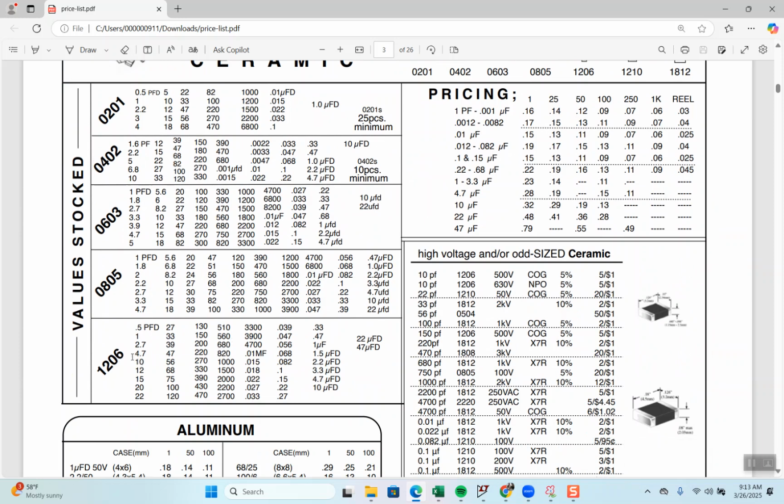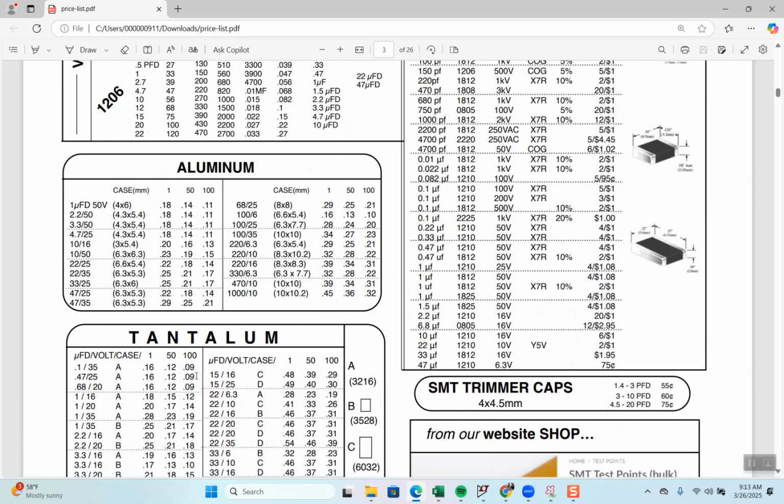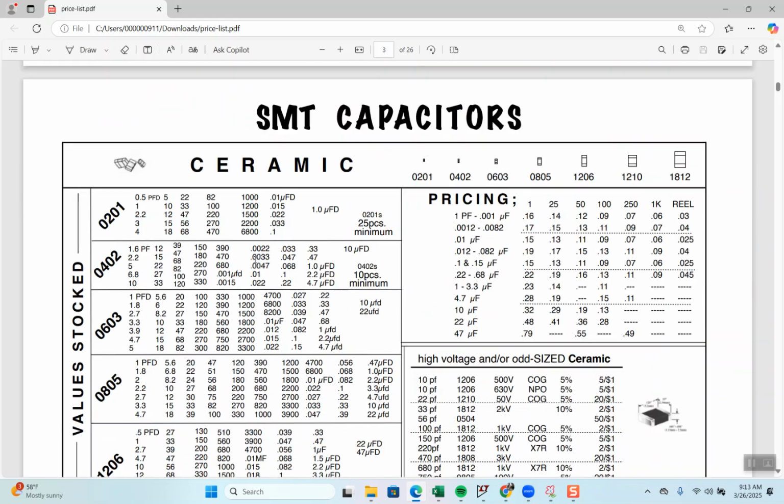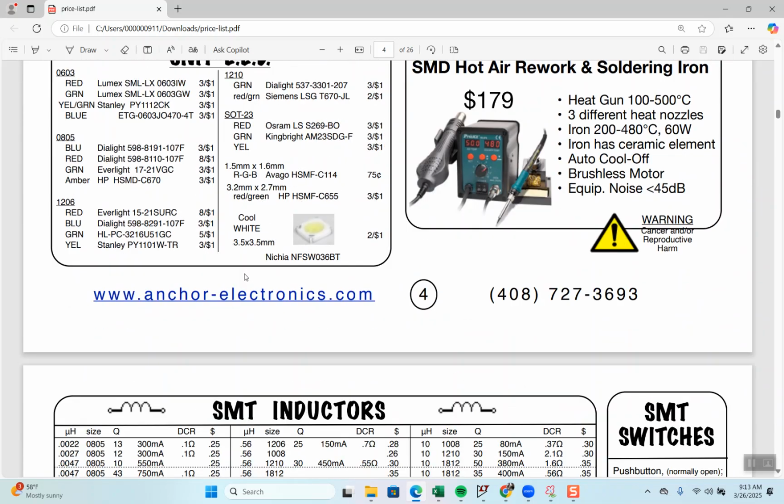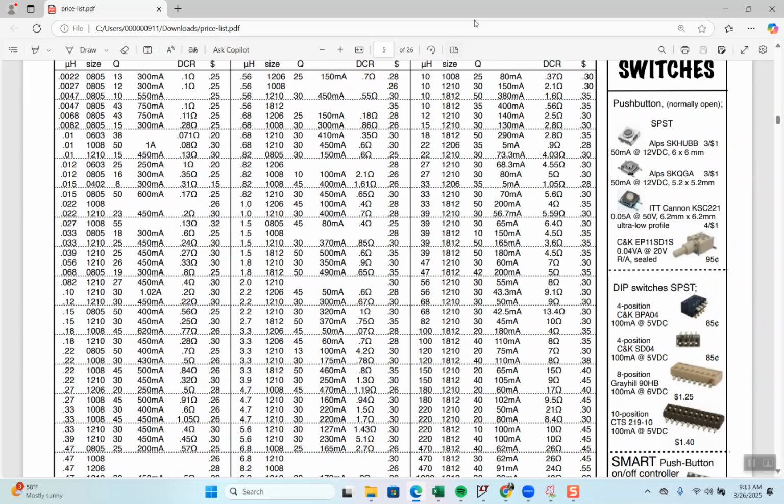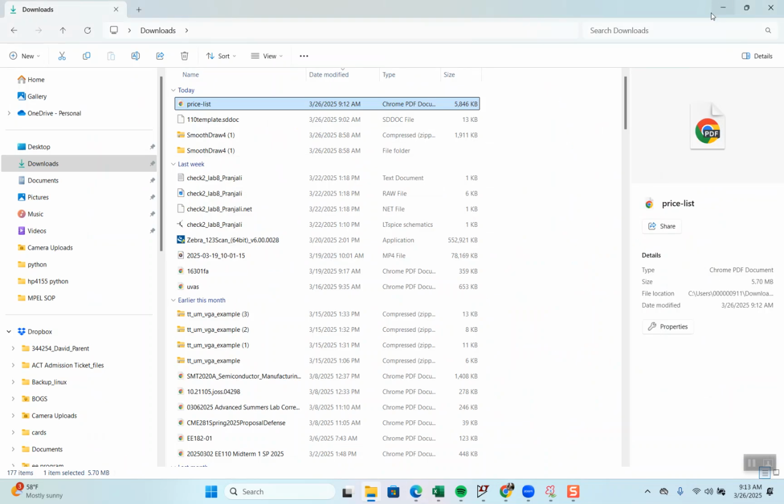And the 1206 has more choices, but that's only because they can be larger, right? So the 0.51, 2.7, 4.7, 10, 12, 15, 20, 22, right? That's kind of the pattern that you can get. And the same with inductors, which are even more limited, okay? And in one of the notes, I just have a capture of this for the relevant thing, all right?